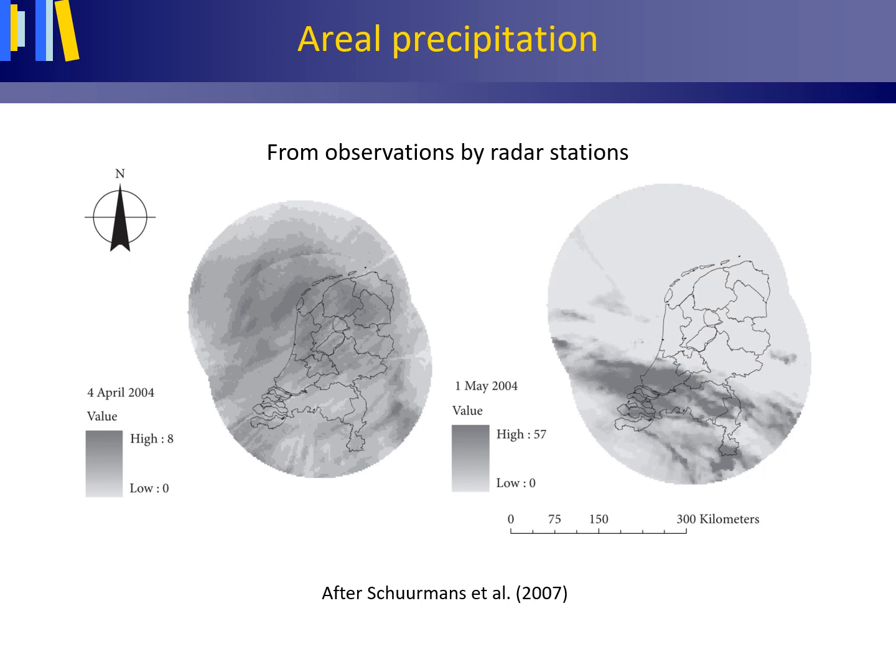Radar can produce estimates of precipitation for time intervals as small as 5 minutes and for areas ranging from 4 to 138,000 square kilometers. As an example, this figure shows daily precipitation values estimated from radar observations for an area of approximately 83,000 square kilometers, including the Netherlands.